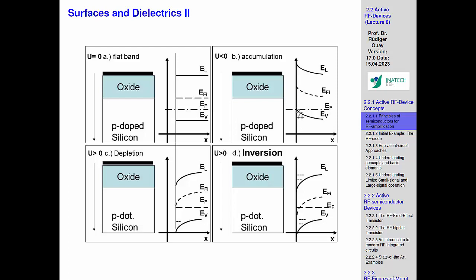So that's something, because in this case we go for p-type doping in the silicon. That has two reasons, because natural silicon would tend to be p-type by its nature, and also we have a reason for that based on the MOSFET. So we could discuss this with electrons, but that is a more difficult case.